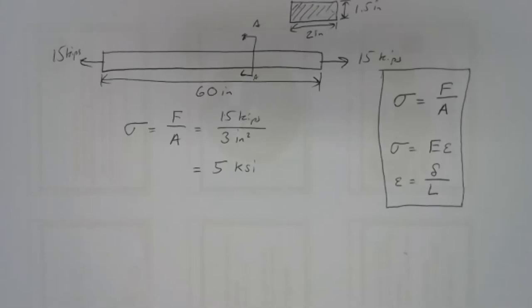If I'm not below my ultimate strength, the problem stops here because we know it's not gonna pass. And in fact, there's really nothing in the table with an ultimate strength below 5 KSI. About the lowest it gets in this table is cast iron. Cast iron has an ultimate strength of 20 KSI. So if this was a cast iron beam, I might be loading it up a little bit much, but it would still be well under its limit. So that's our ultimate strength. So I know it's going to be safe there.